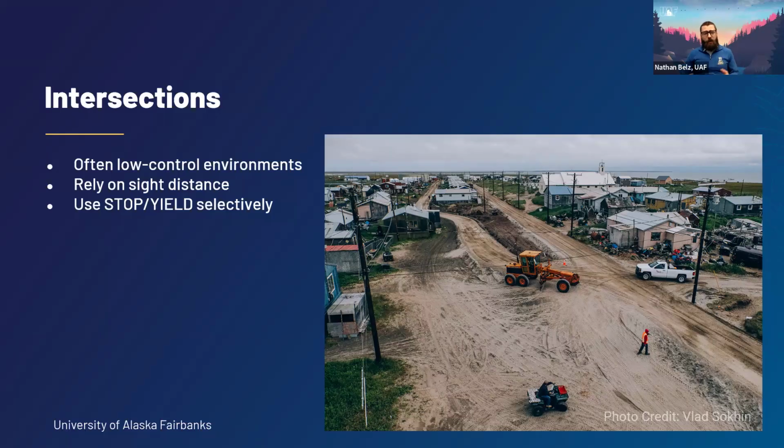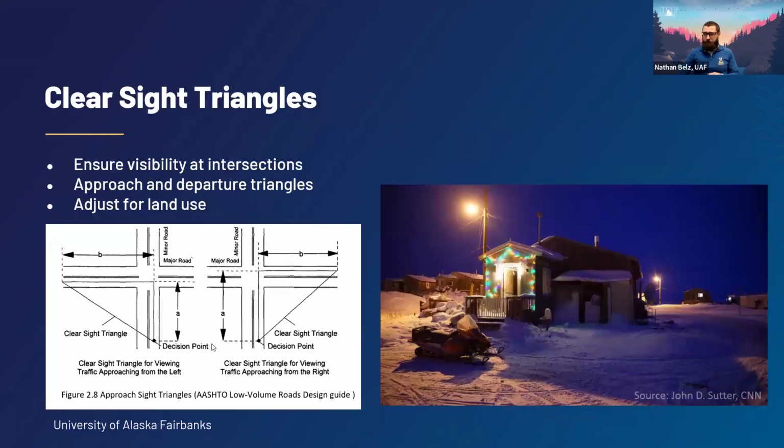And then in the case where you either have obstructed or restricted views that would require a road user to stop to adequately observe traffic, or if you are in or near a school zone, or areas with significant pedestrian or other multimodal user considerations, one might consider using stop signs in that case.